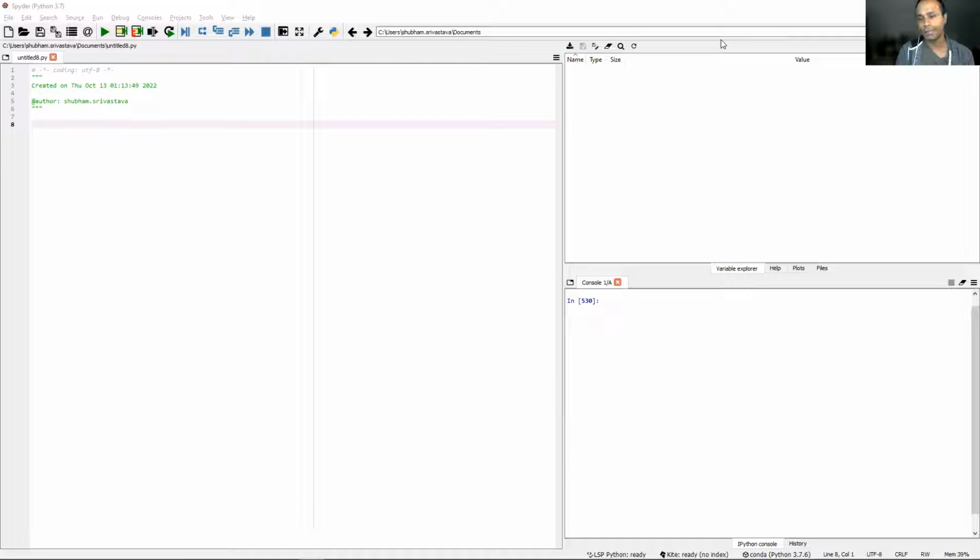So let's jump on to the first set first. For that, we will have to first select a reaction from, say, the GRI mechanism so that we can test out these functions. And this will be done on the Python console. Let's start with importing Cantera. And let's define an object.